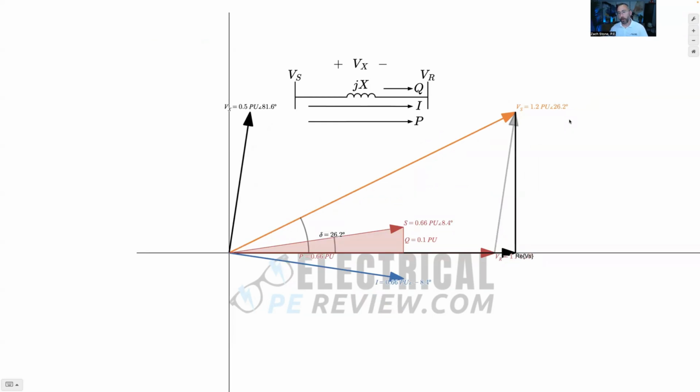What happens if a generator, as more load comes on a generator, how does a utility generator push out power? Power flow and synchronous generator theory, it's extremely similar. It's entirely interwoven, same formulas. If this was a synchronous generator, this would be our internal voltage EO, this would be our synchronous reactance, and that would be our terminal connection E. So these same leading, lagging, overexcited, underexcited relationships, same exact relationships as power flow. It's like looking at the generator as its own bus, generator reactance as the conductor between them, the stator reactance, and then the terminal E as the receiving bus.